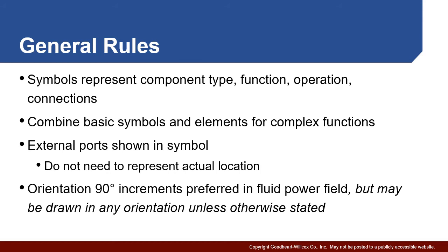In general, you will only see the external ports shown on a symbol. So how does it connect to other components? You don't tend to see the internal functions unless, of course, you're looking at a cutaway. In terms of where those ports are, these are shown in symbolic form, so you really don't have to represent where they actually are located on the valve. Valves differ from manufacturer to manufacturer, but we're mostly worried about function, not so much about the actual appearance.